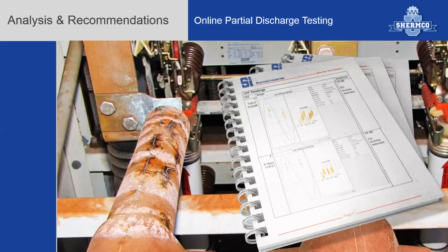Those of you that do infrared studies, an infrared or thermography study helps you determine bad conductive connections, loose hardware by showing IR drops. And this is also a form of predictive maintenance. Partial discharge is sort of like the peanut butter to the jelly of thermography studies. One is showing you mechanical damages or mechanical failures occurring. The partial discharge shows you trending or events that are happening in the insulation. So again, thermographers armed with partial discharge sensing and detecting equipment is kind of that 1-2 punch of the reliability management, predictive management world.